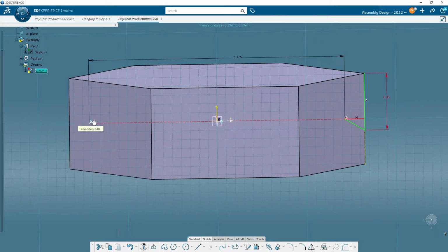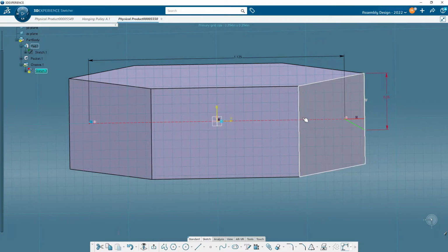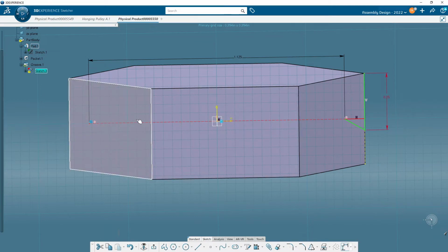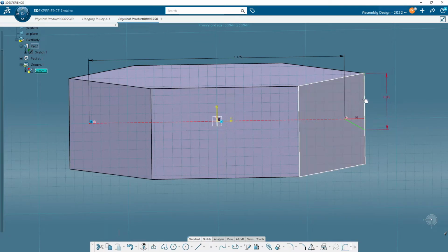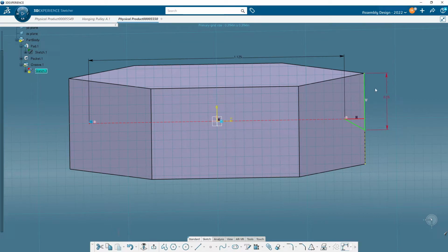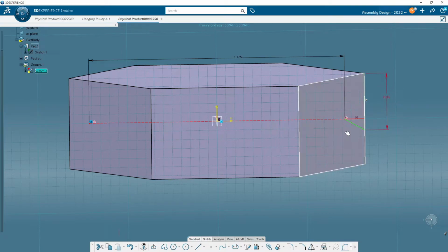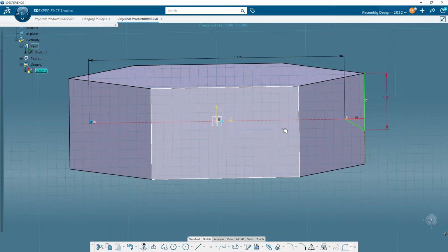Now, a lot of times if I delete that coincidence, it might just sit here, and then I go ahead and reconstrain it to the thing I'm supposed to constrain it to. But imagine that this problem right here is holding this triangle from snapping up to the top of this point to make this value here that's red, the 0.05, that's not correct either. It can't do it. It's red. It's trying to make this line 0.05 from this tippy top to down here. It is not really this long. It's just saying, I can't do this. I'm trying hard to do this, but because of this red right here, it won't let me.